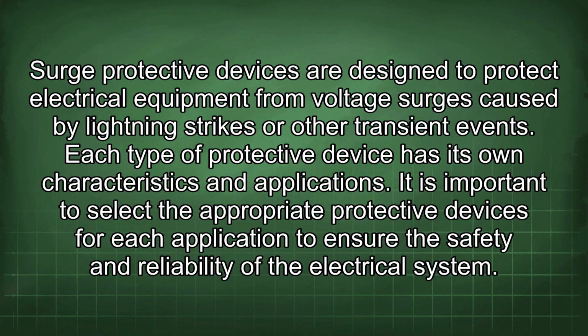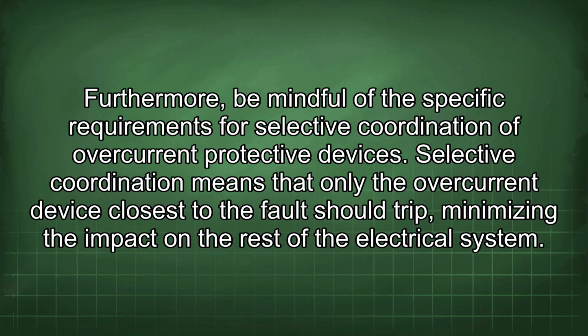It is important to select the appropriate protective devices for each application to ensure the safety and reliability of the electrical system. Furthermore, be mindful of the specific requirements for selective coordination of overcurrent protective devices. Selective coordination means that only the overcurrent device closest to the fault should trip, minimizing the impact on the rest of the electrical system.